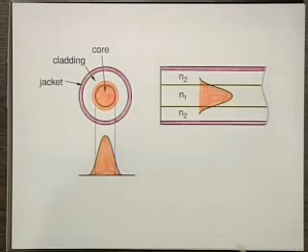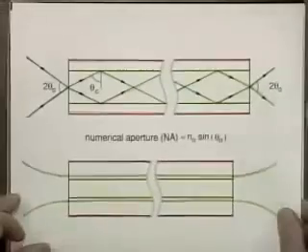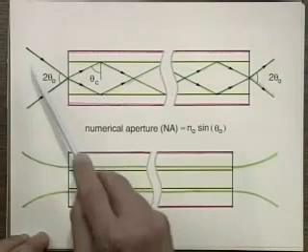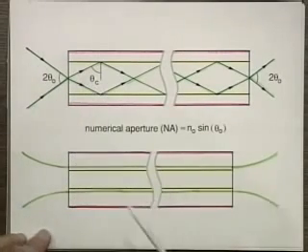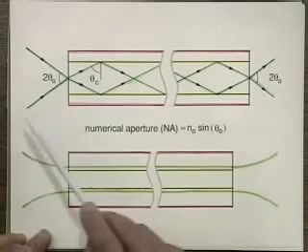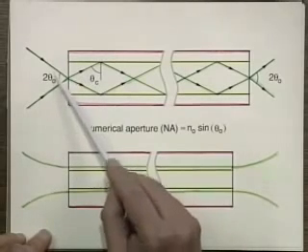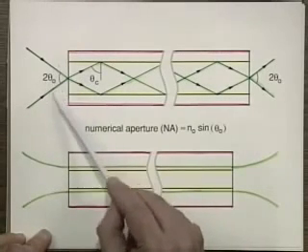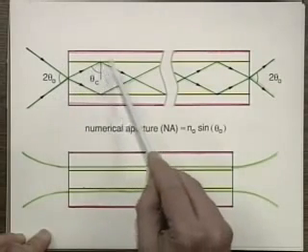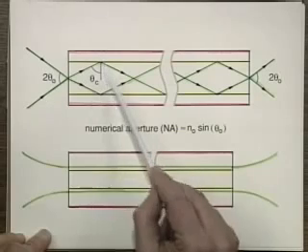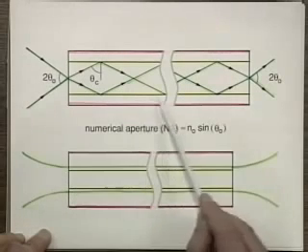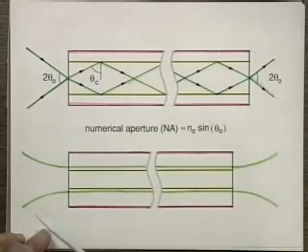Now, how does the light look when it comes out? Let's go back to the ray picture. Remember we said that the angle has to be either equal to the critical angle or bigger, and that determines the acceptance angle going in, because rays of light coming in outside this cone will not undergo complete total internal reflection, and will be in trouble because they won't propagate very far and they'll be attenuated.